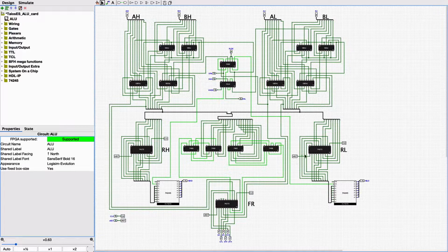And that is simply to tell you whether the contents of these 2 registers, there are 3 flags per register, that's why you see 6 here, whether the contents of these 2 registers are 1, 0, and then the zero flag is active, whether the carry from the ALU here, the carry out that you see here, going into the flags register, tells you whether the carry is active, because for instance, if you're doing an 8-bit addition and you're adding, I don't know, 250 plus 10, then you have an overflow, because the result will be higher than 255, and that doesn't fit into 8 bits, so you have an overflow, and then the carry flag low, this one, will be active, telling you that there is an overflow.